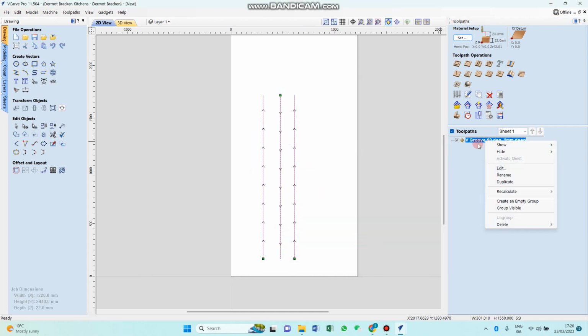And now obviously anyone buying the machine will get that toolpath template. You can adapt that then to, if you want different depths or a different tool, whatever. But that's also applicable to all types of V tools. You can use an end mill for that as well if you want, or even a form tool to do some nice kind of molded looking beads going along stuff.